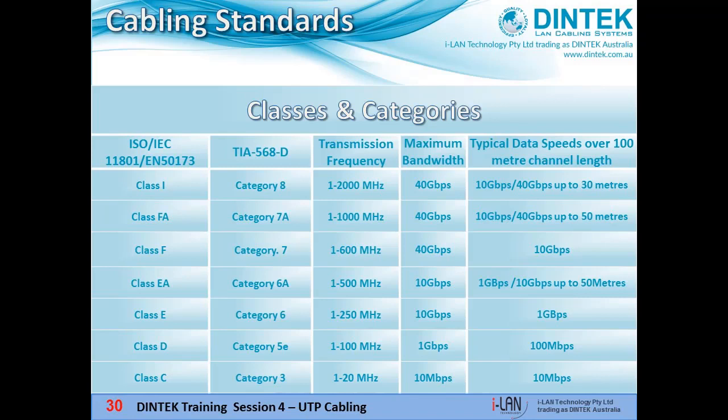What that means is we may very well be able to achieve some very respectable bit rates over lower rated cables, but we won't necessarily achieve it over the same distance due to the lower standards of the cable. For example, Cat6a can support 10 gigabits a second over 100 metres under its standard, but if we try 10 gigabits a second over Cat6, which only has to support 500 MHz up to 55 metres under its standard, we might only get 30 or 50 metres or so, depending on other external impeding factors like crosstalk and EMI and so on, and other factors that affect SNR. If we try to transmit data at 10 gigabits a second over Cat5e cable, we might only get 20 or 30 metres. Beyond that, the speed will drop off sharply.